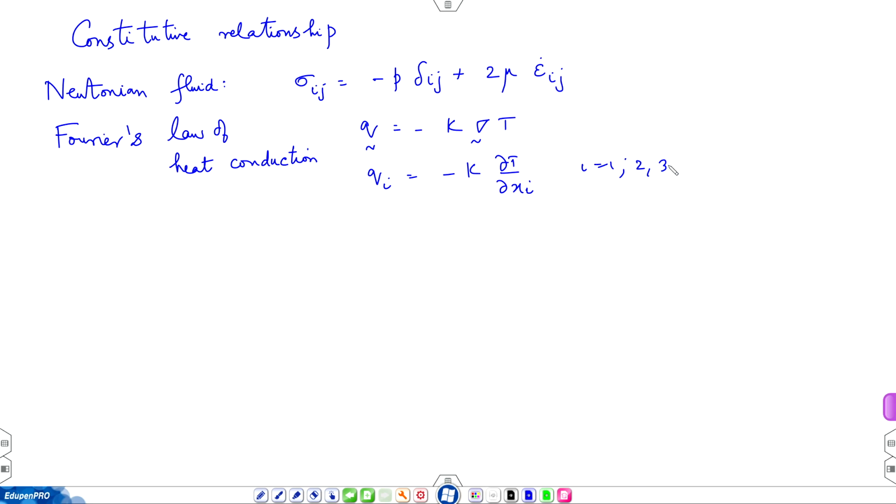So, if your fluid medium like blood is not Newtonian, we call it non-Newtonian. Similarly, materials in which Q is equal to minus K gradient of T is not satisfied are called non-Fourier media. But for the commonly encountered materials, Fourier's law of heat conduction is known to prevail in the sense that thermal conductivity can be well defined.